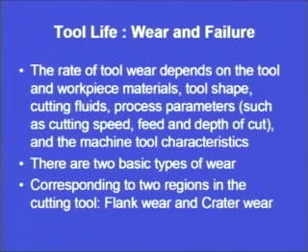Moreover, tool wear is not only going to affect the tool life, it is also going to affect the surface finish of the product that we are machining. It is also going to affect the dimensional accuracy. So, we have seen that tool wear takes place because of certain conditions, which lessen the tool life and also affect the quality of the product. That was the summary of what we covered in the last lecture regarding tool life and failure. From there, we will now carry forward our discussion regarding tool life, wear rate and failure. Now, the rate of tool wear depends on the tool and workpiece materials.